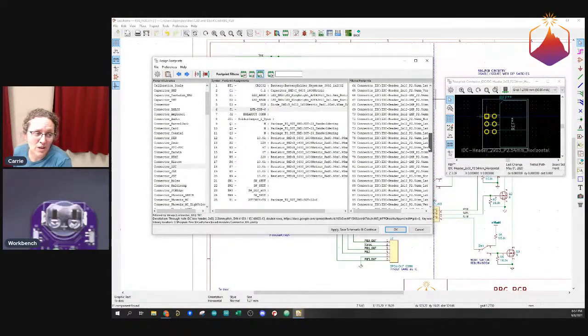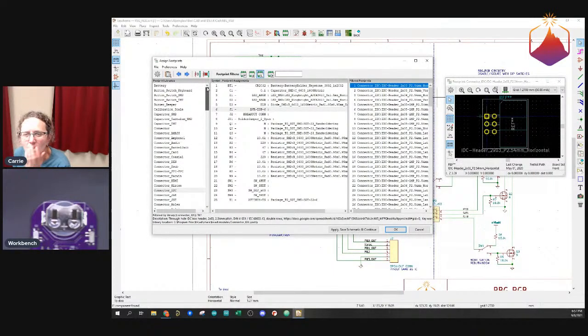We of course need a surface mount version, because we can't have through-holes on this board; it would mess up our lovely graphics. So everything has to be on one layer on the backside and all surface mount, so that nothing pokes through. They do not appear to have it under IDC connectors, which is the style of connector that it is. I'm wondering if there's an Arduino library or an ISP. ISP stands for in-circuit serial programming.